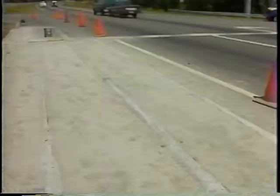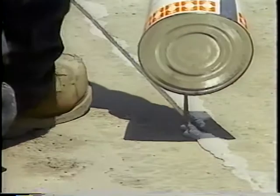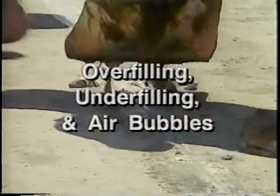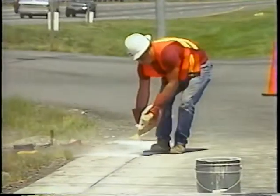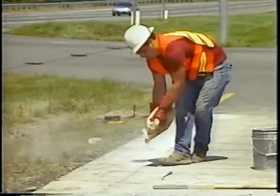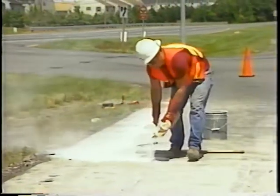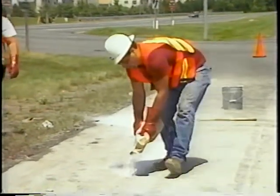Whichever method is chosen, apply enough sealant to fill the saw cut completely. A trowel or similar tool should be used to remove any excess sealant. Remember, overfilling, underfilling, and air bubbles in the sealant can all cause detector failure. Finally, some agencies coat the newly applied sealant with sand or talc to prevent tracking the sealant during its curing stage. It is critical that you plan your installation process in such a way that the saw cutting, wire installation, and loop installation are completed within the same day. Saw cuts should not be subjected to traffic flow.